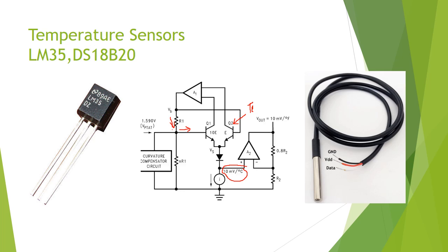For 1 degree Celsius, there will be a difference of 10 millivolt, and that 10 millivolt can be measured and sent through your data pin. Suppose at 25 degrees Celsius this data pin has, say, 3.5 volt.